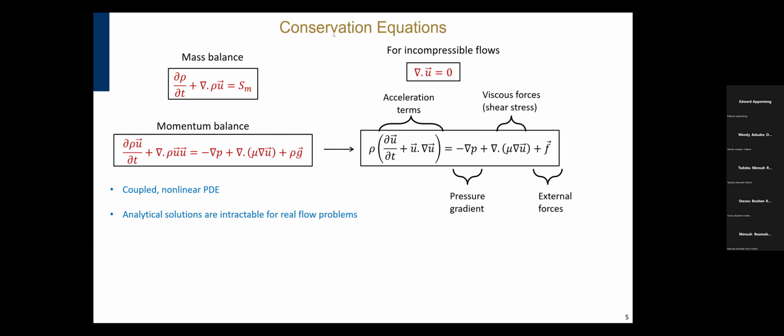Yeah, okay. I quite remember when I was once using a CFD software, most of the times whenever I'm solving a problem, the results I'll be getting will be diverging instead of converging, and I sometimes get stranded on that aspect. So I wanted to know if the meshing quality affects the results.